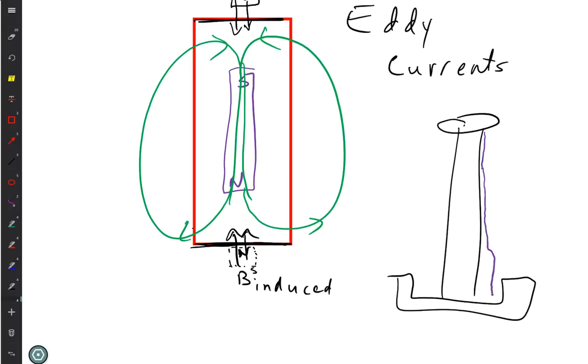And what you actually have is that's a conducting material, and you have magnets on either side of it. And as it falls, it's going to create eddy currents in that thing that's sticking out that will act as a brake. And as you get down to the bottom, they have a design so the braking is going to get much bigger. That's a good thing, because what if you're on top and they just release you and the power goes out?